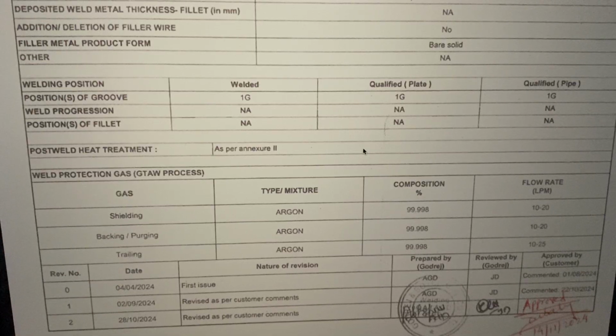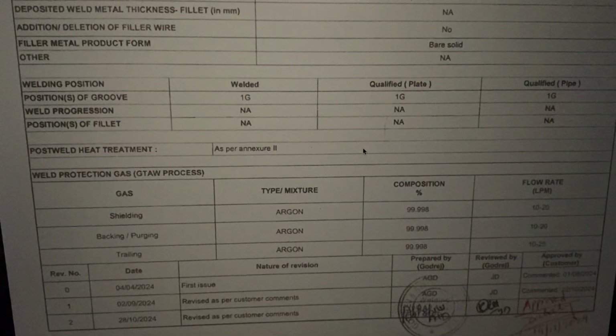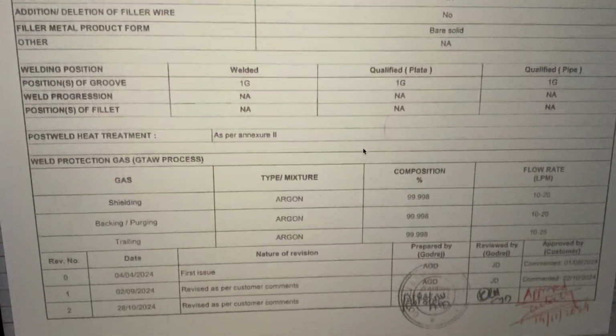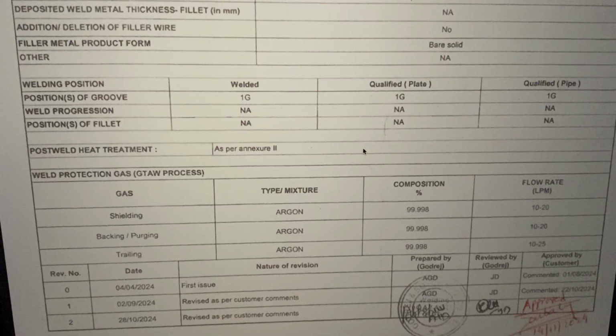Are we going to create a particular atmosphere by using a box which is made out of titanium sponge or a nickel sponge? All these are becoming essential, and that's why we have dwelled upon this. It is not only specifying, but getting further into as many details about purging. So if you are going to have a purging, how has the purging arrangement been done, whether there was a copper backup, then what diameter of the purging holes, at what intervals we have put them,